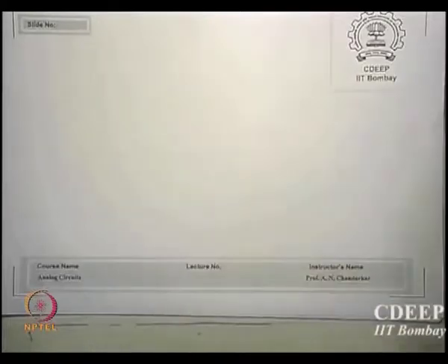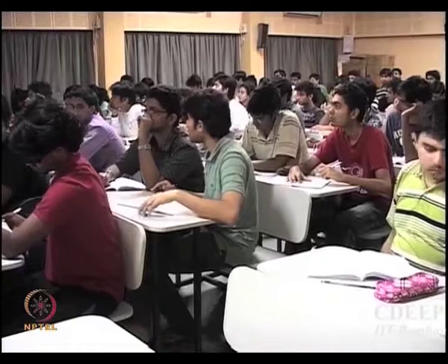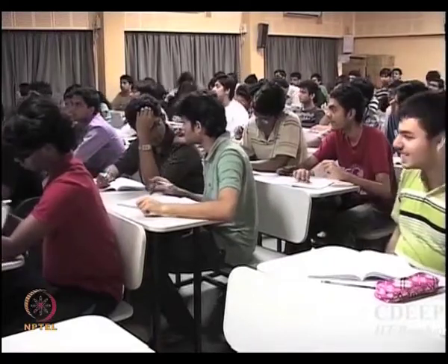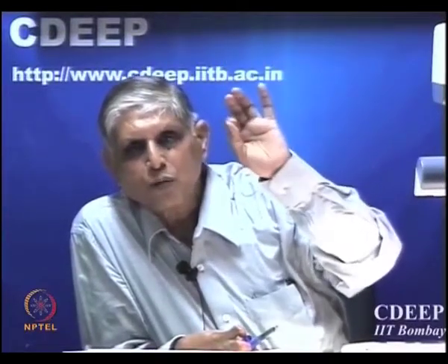Please look at it, this solution I do not want to do, I just want to show you how we worry about solving a network. Is that clear? What is the game? Just draw the equivalent circuit, put voltages as given to you and see which loops you are getting to solve. Solve the 2-3 equations. If 2 unknowns come, 2 equations, you should always be able to solve all parameters in terms of the others. That is the technique we will follow throughout the course.